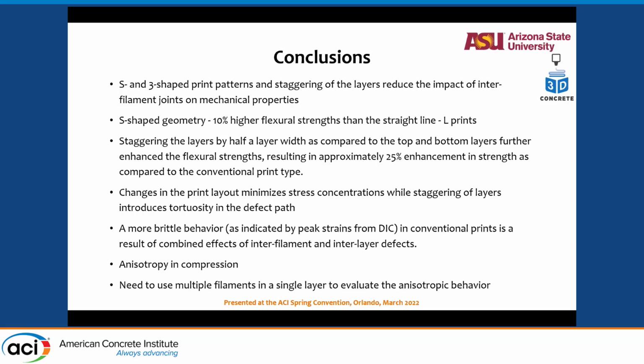You have higher flexural strength compared to the regular prints. Again, staggering by half a layer width. I forgot to tell you that all the layers were staggered by half a layer width, like you do masonry with bricks staggered, right? Very similar idea. Changes in print layout minimize stress concentrations, while staggering induces tortuosity in the layer path. And we have microscopy, which I did not show here, to show how the crack path changes.